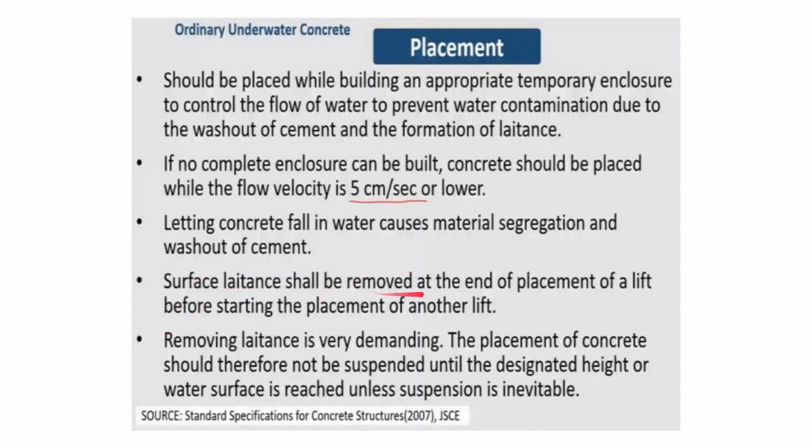Surface laitance shall be removed at the end of placement of a lift before starting the placement of another lift. Okay, so this is important because if we don't do this, and we just place another lift of concrete, that will result in cold joints. Okay, that is the segregation of both the layers because of the difference in water cement ratio. Because a lot of water will be present upwards. Okay, so that will lead to segregation and difference in layers. Okay, spalling of layers.